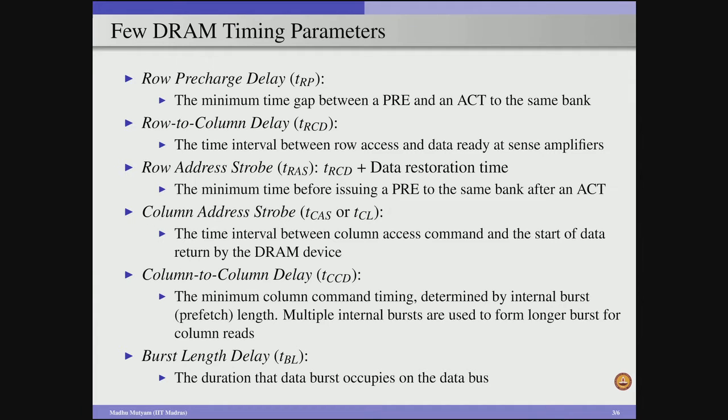So we internally transfer the data from these DRAM arrays in a collection of internal burst length which is specified by the prefetch, and once we have this data, then we will pack everything into our data output unit, and from there we can transfer the data onto the data bus by using our external burst length, which is specified by the TBL, which is going to be discussed as the next point. The TBL specifies the duration that the data occupies on the data bus. So as a result, this data bus cannot be available for performing any other operation within this TBL time.